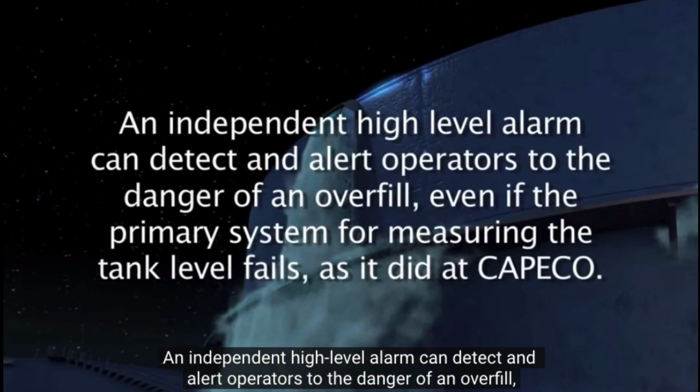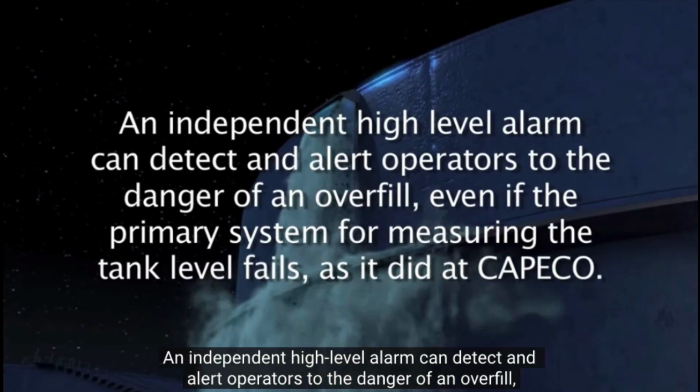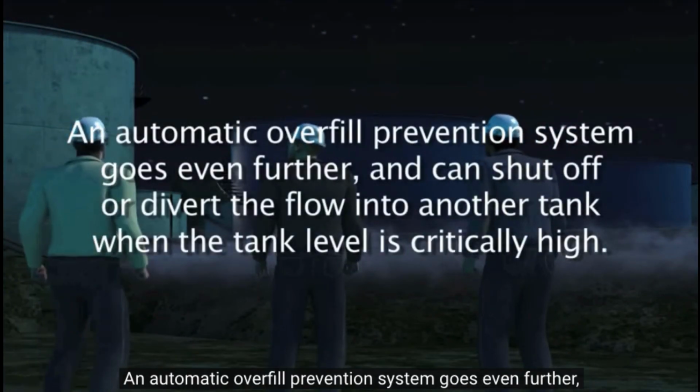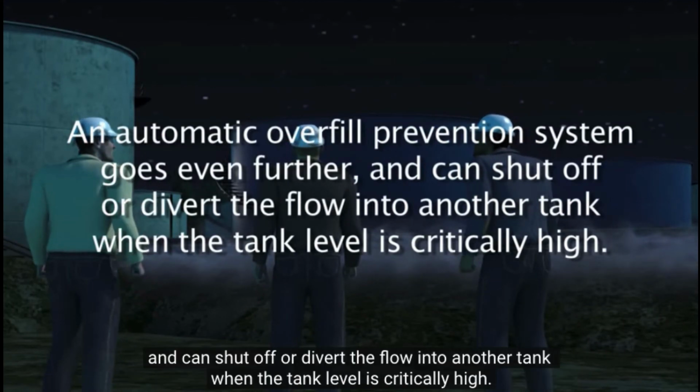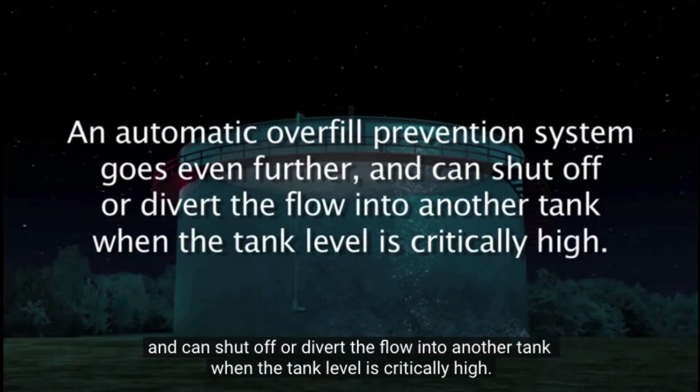An independent high-level alarm can detect and alert operators to the danger of an overfill, even if the primary system for measuring the tank level fails, as it did at Capeco. An automatic overfill prevention system goes even further and can shut off or divert the flow into another tank when the tank level is critically high.